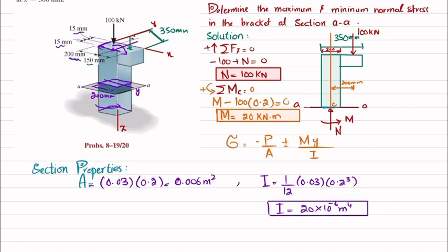Okay, you have A and I, so you can see that due to this moment, this will bend, with this portion in compression while this portion is in tension. So this left side will be in tension, clear, and this right side will be in compression. So we will take sigma L, which is the left side and that is in tension, equal to minus P divided by A plus M into Y divided by I, tension.